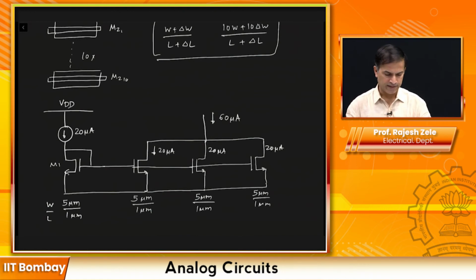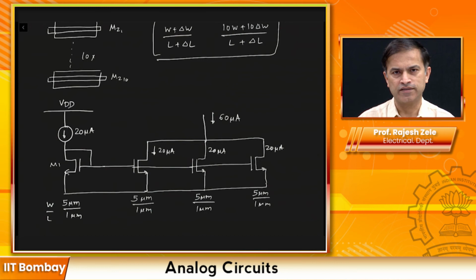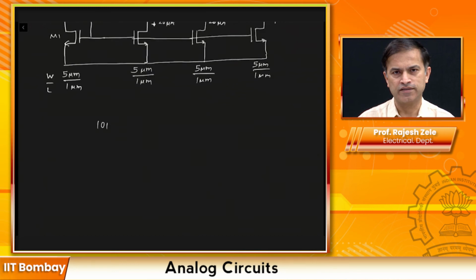Okay, so one simple example: let's say I have a reference current of 10 microamps coming from somewhere, and then I would like to reproduce, let's pick 22.5 microamps for some reason. So here, by inspection, you could quickly tell what the common factor is.